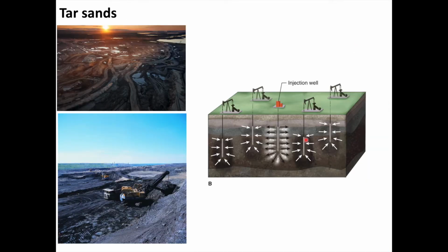Let's go into it a little bit more. A lot of energy and water resources and processing go into extraction of synthetic oil from the tar sands. Some heavy oils are too viscous to be extracted directly by pumping. About 60% of the oil extracted from the tar sands is stripped by surface mining, and for this, 2 barrels of water are needed for every barrel of oil produced. This mining process generates tailings that are a mixture of water, mineral residue, and unrecovered bitumen, and can leach toxic materials into surface and groundwater supplies.